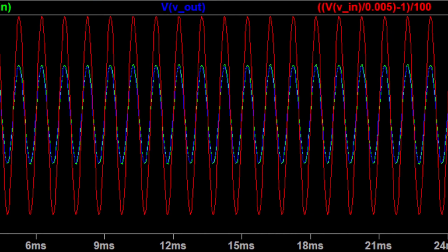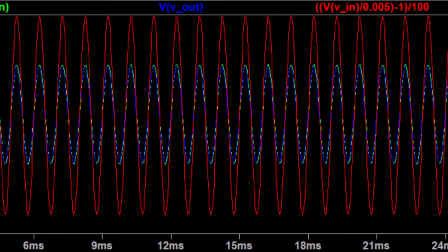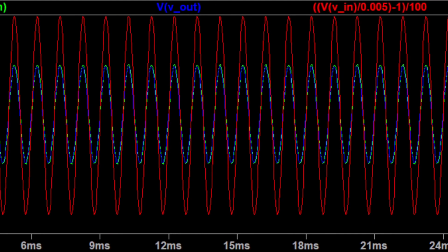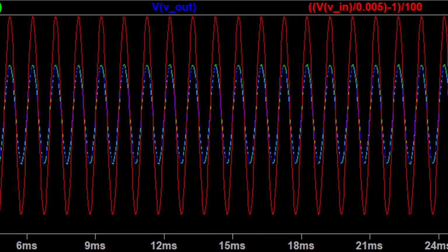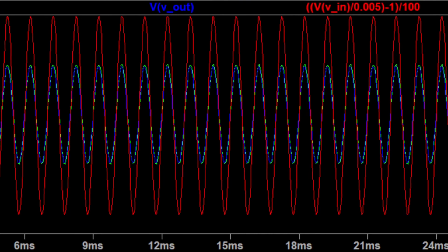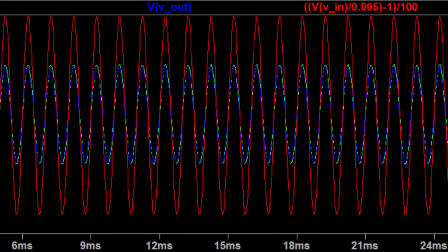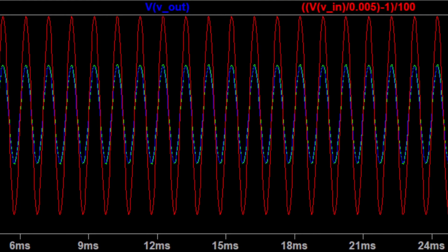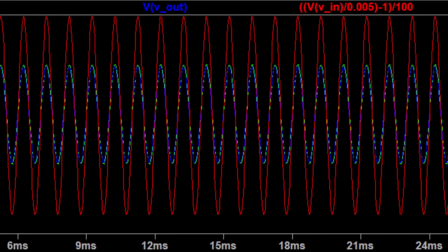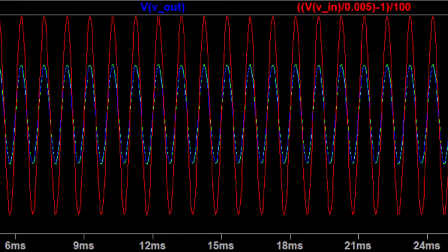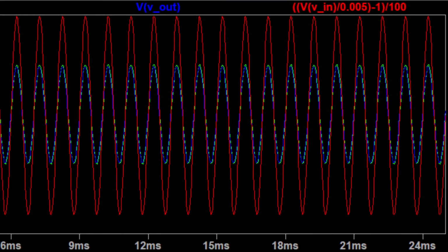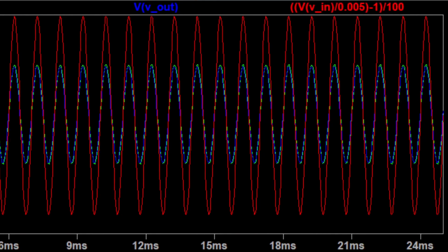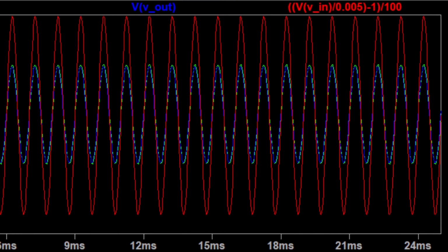To determine the gain results in this simulation, I reused the same equation we had done to complete the calculations in earlier steps, but it was only as a reference point. To actually do the gain calculations, we compare the amplitude of the output divided by the amplitude of the input. You can do those measurements by looking at the points on this graph and comparing it to the values given by the gain equation typed up in red above.